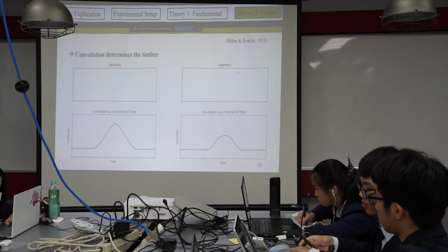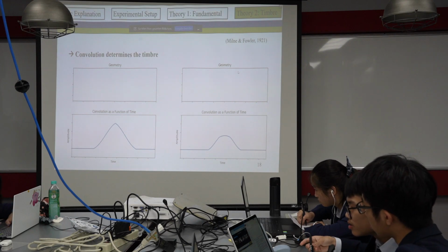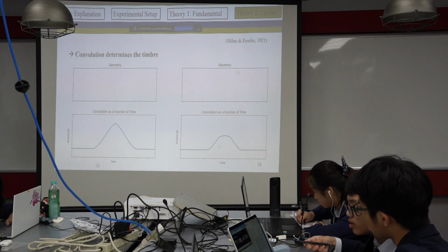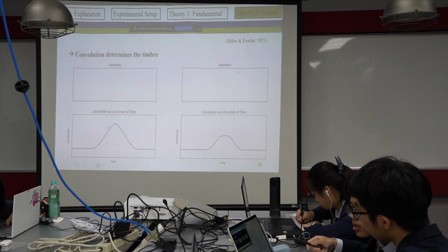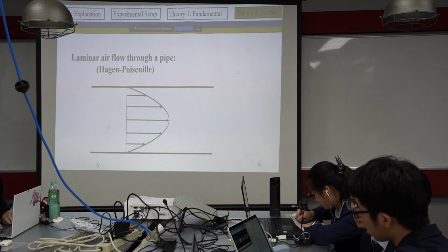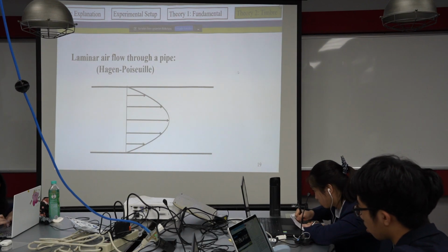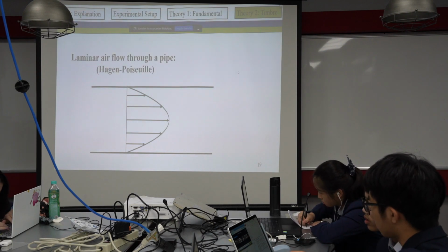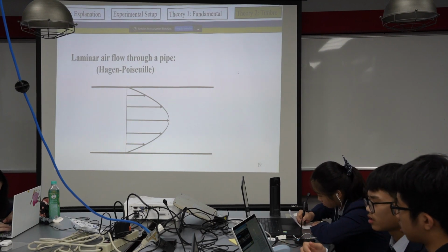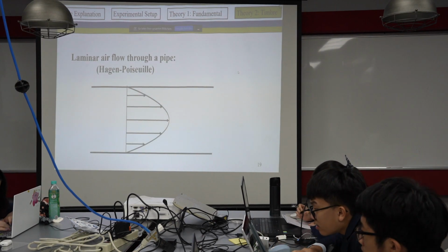What this theory does not consider, however, is the convolution of two different sized holes, which we can see looks quite different to the one of two equally sized holes, and it does not account for the velocity profile through the pipe. Because the velocity profile of a laminar flow through a pipe is approximately quadratic, the resulting convolution cannot simply be done with two holes.